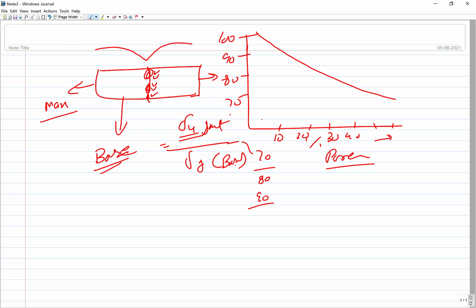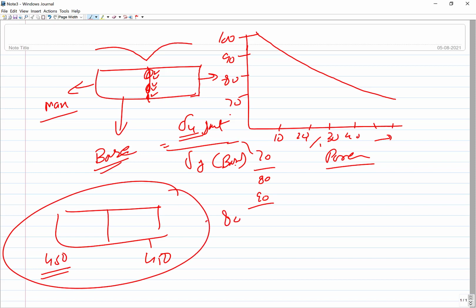Second is that you started with a base metal which had a strength of say 450 MPa in the beginning, on both the sides. After the exposure at a high temperature of say 800 degrees centigrade for 2 hours, you may find that everything has changed. Now the structure has coarsened, the metallurgical properties have been modified. So now you will be left with say 400 MPa. So in general, the base metal properties as a whole have been compromised, which may not be acceptable from the design purpose or from the performance point of view.